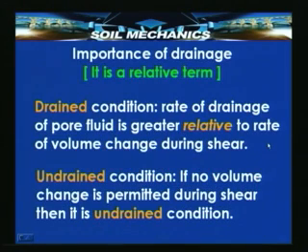And what is this drainage? Why is it important? It is important because it is a relative term. When I say there is drainage provision during a test, what it means is that the rate of shearing is such that water has enough time to flow out of the soil.